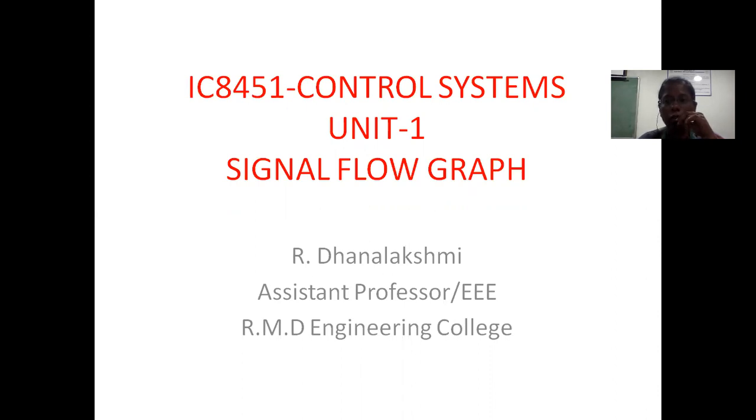The signal flow graph tells you the flow of signals from one node to another node, that is, from the input point to the output point. Like the block diagram reduction technique, where we get a transfer function, in the same way using the signal flow graph we are going to obtain the transfer function of the given system. We know already that the transfer function is the Laplace transform of output by Laplace transform of input, assuming all initial conditions to be 0.